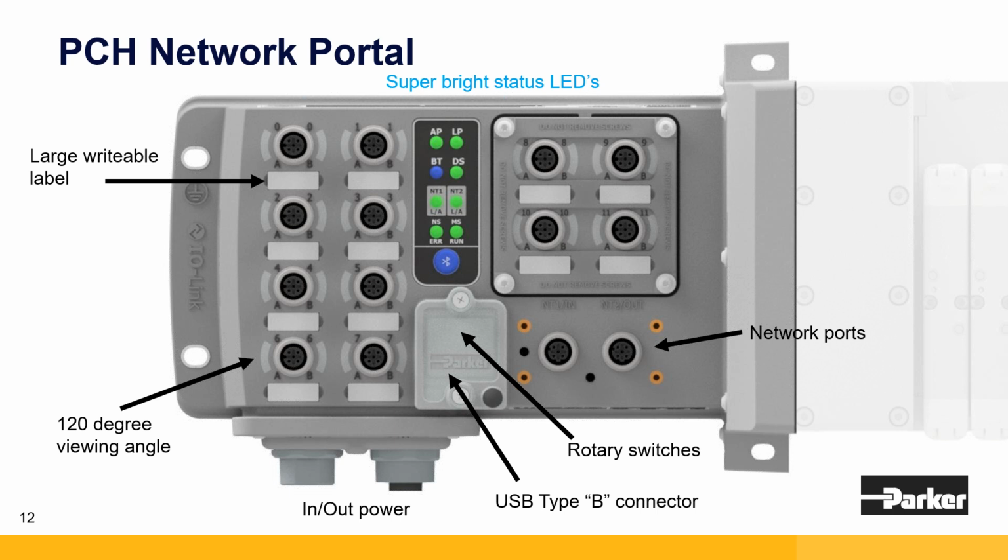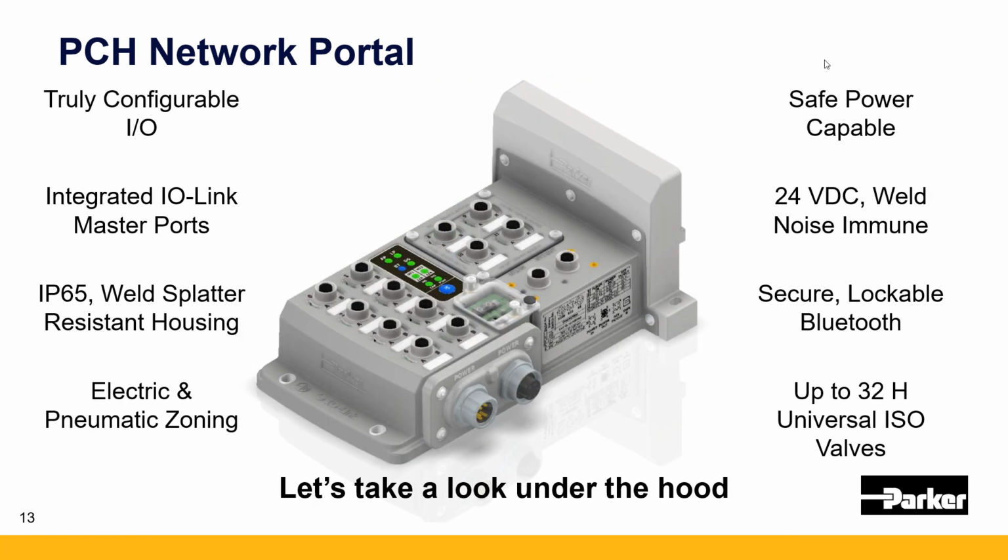We designed a lot of circuitry into here to the point where we could ask this question over here on the left of the slide. I'm going to point out this port here, our port 0, our top left port. And I want to ask you, is that a digital output? Is it a digital input NPN? Is it a digital input PNP? Is it IO-Link A or IO-Link B? The answer to that is it can be all of those things.